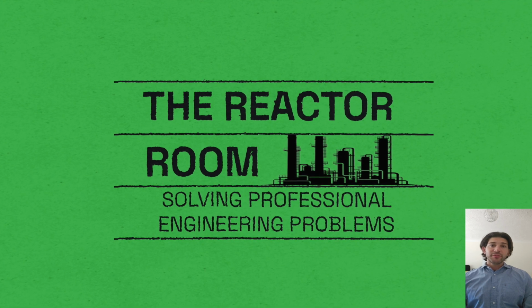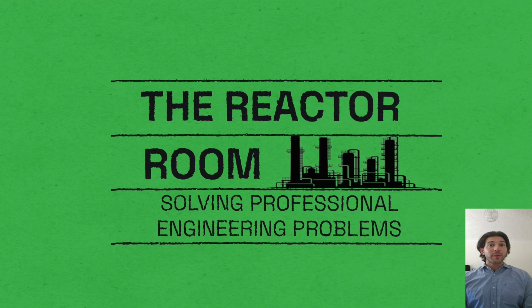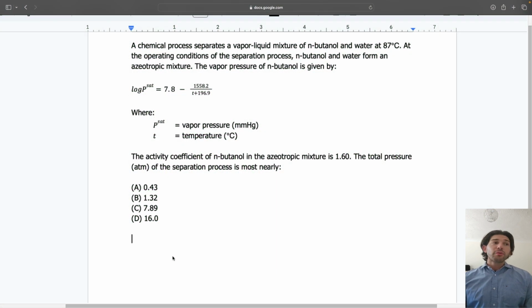My name is Zachary Brownstein, and in this video we will solve the following problem. A chemical process separates a vapor-liquid mixture of N-butanol and water at 87 degrees Celsius. At the operating conditions of the separation process, N-butanol and water form an azeotropic mixture. The vapor pressure of N-butanol is given by the following Antoine equation. The activity coefficient of N-butanol in the azeotropic mixture is 1.6. The total pressure in atmospheres of the separation process is most nearly...